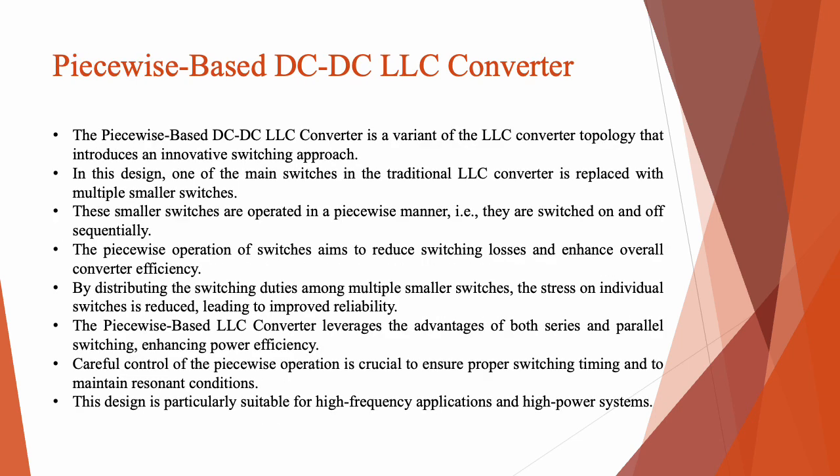So now the piecewise based DC-DC LLC converter. The piecewise based DC-DC LLC converter is a variant of LLC converter topology that introduces an innovative switching approach. In this design, one of the main switches in the traditional LLC converter is replaced with multiple smaller switches.